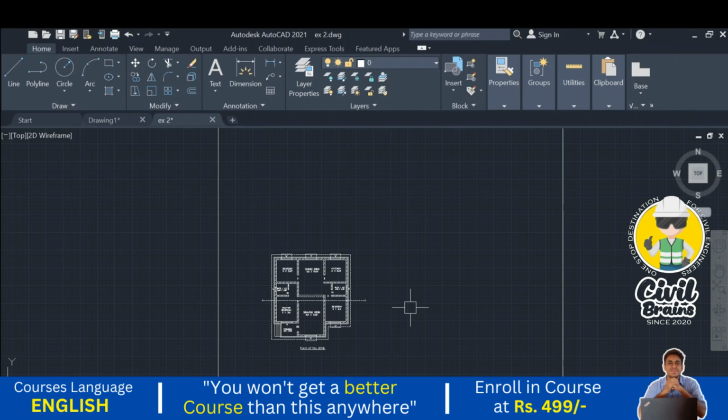If it is BBM or stone masonry, depending upon that we need to hatch it, or if it is a concrete wall, then we need to show concrete. If columns are there, then we need to show the columns also. This is the basic presentation drawing which we need to give with these minimum details on the site. Beyond that, we can add furniture layouts, plumbing, and all these things. Okay, so we'll go with the next part of this drawing.